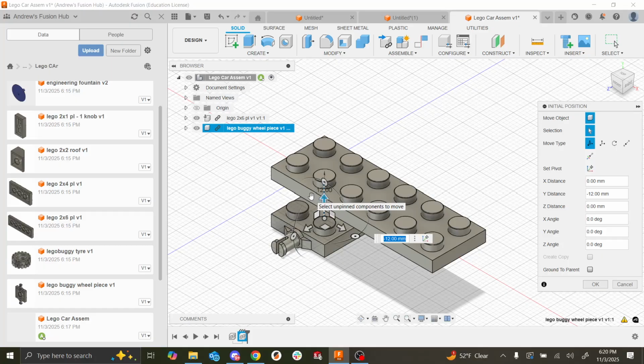Similar to when you're creating sketches, I sometimes make the sketches purposely look off and then I add geometric constraints later. This is the same concept. So I typically move stuff a little bit far from where they're going to be when I place the part. So this looks good. I'm going to confirm it.